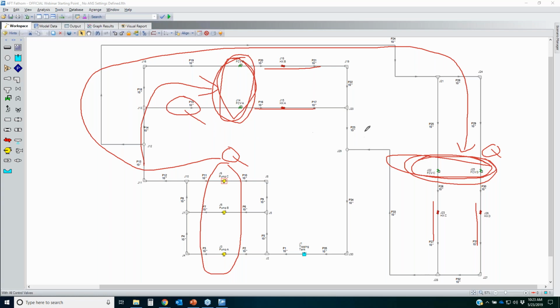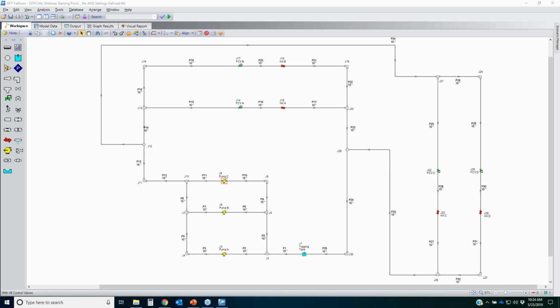So this is an issue in mathematical modeling for anything that you're trying to solve, where you've got known flow rates for your boundary conditions. You can calculate a pressure drop in your system in order to meet those flow rates. However, what's the pressure right here, or the pressure here, or the pressure in this pipe right here? There's no way to know, because there's a number of multiple solutions that can exist which will be able to meet those flow rates. So this is where you have to have a reference pressure, which is completely outside of the scope with today's webinar.